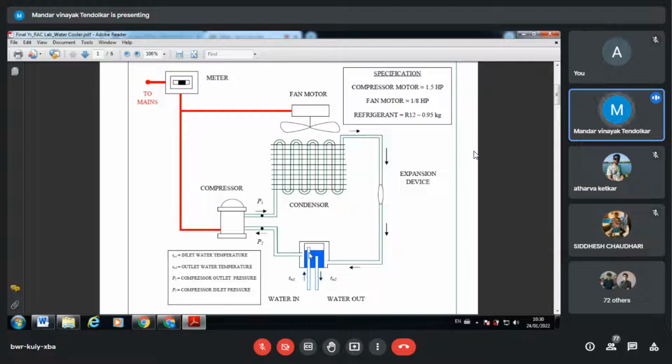So that is why for the refrigerant the phase is getting changed. For the water there is no question of any phase change. It is rejecting the heat as a sensible one. Let's take some random values. Water is entering at 30 degrees Celsius, getting cooled to, let's say, 15 degrees Celsius. So this 30 to 15 is the sensible part, and sensible part means m dot into Cp into delta T. Cp of water is constant.